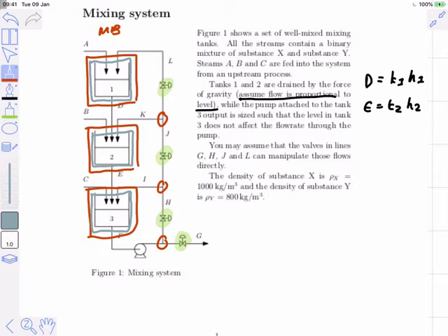But what you'll find is, I'm going to just tell you the way that I think about the problem. As I've mentioned before, I like to have many equations that are very short in my models, rather than a small number of equations that are very wide. So I bias away from early substitution, and I bias towards having a reliable set of nomenclature. So when I solved this problem in Modelica, I had a fraction for every single stream. So I had an XA, XB, XC, all the way through to XL.